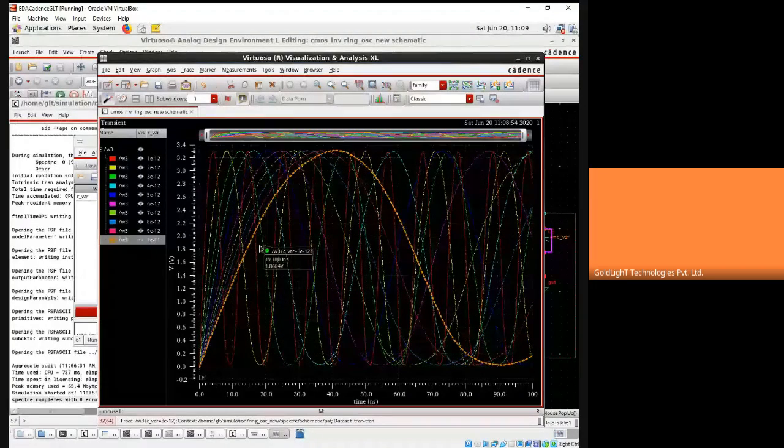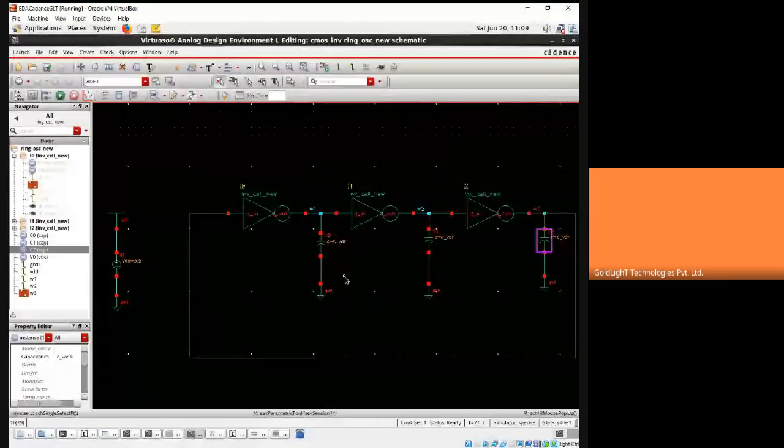So this particular circuit, this ring oscillator, can be modified into a VCO by varying the capacitor, by connecting some CMOS circuits here, so that it can act as the VCO, voltage controlled oscillator, that can be used in ADC and PLL. So many applications, mixers, and a lot of applications are available.